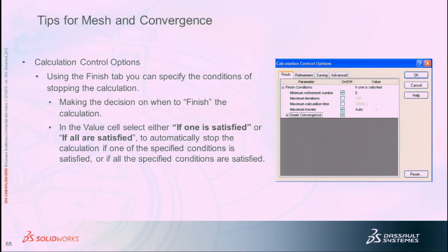Now, what I'd like to do is take everything that we talked about with mesh and talk a little bit about convergence. I've kind of implied it, talked about it a little bit, but just to give you an idea now, as you know, we talked about computational fluid dynamics. There's no closed form solution, so they solve it by solving the right hand part of the equation and the left hand, and they do a time marching technique to try to get it equal. They never exactly equal, so that's why we have this issue with convergence and trying to decide when to stop a solution.